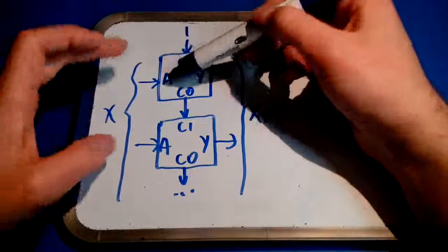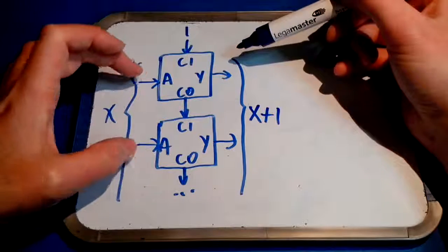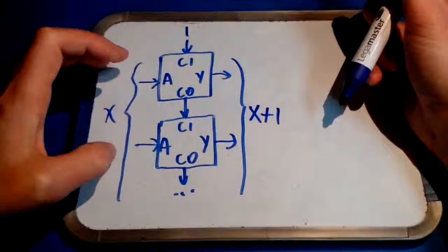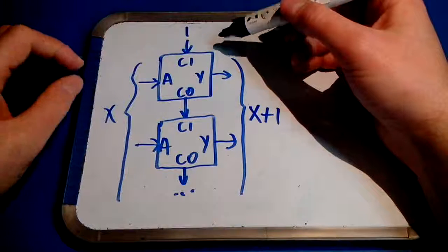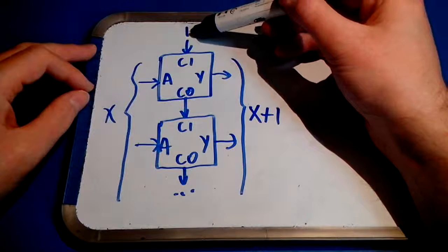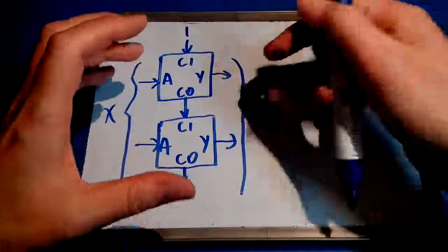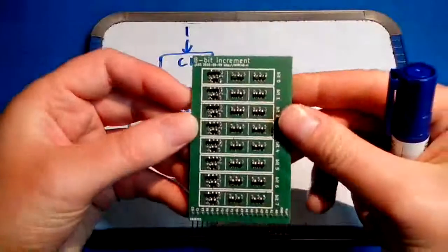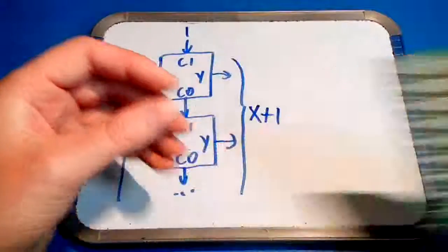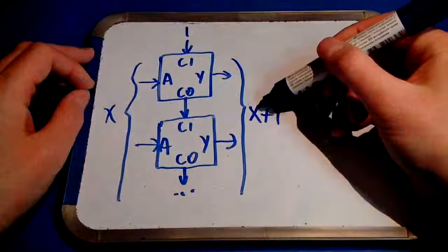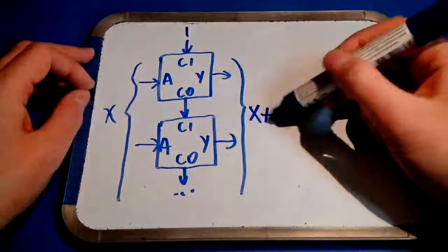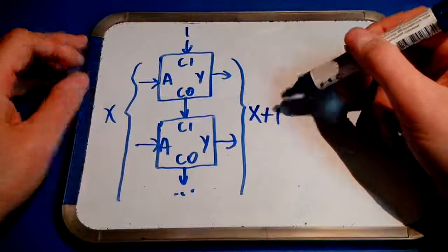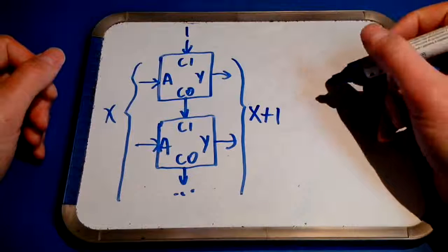So it has an array of 8 inputs which form a binary number, the input number. It's half of the address actually in context of the CPU. It has a carry in input for cascading two of these modules together, right, because there are two. And it has an output which is also a binary number, which is used as the next program address.